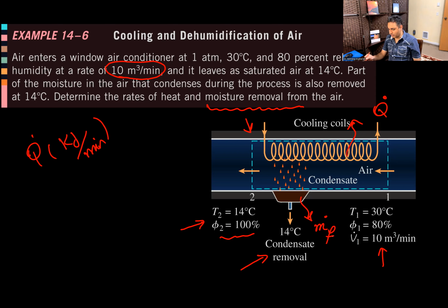So I can show it by m dot of F, basically, because it becomes liquid, right? So I can show m dot F as the liquid. If you're familiar with thermodynamics, you know what I'm talking about. Why did I use subscript F? Because, in the steam tables, when the quality is 0, we show everything by sub F, right? Like the h sub F is the enthalpy of saturated liquid, for example. That's why I'm doing this.